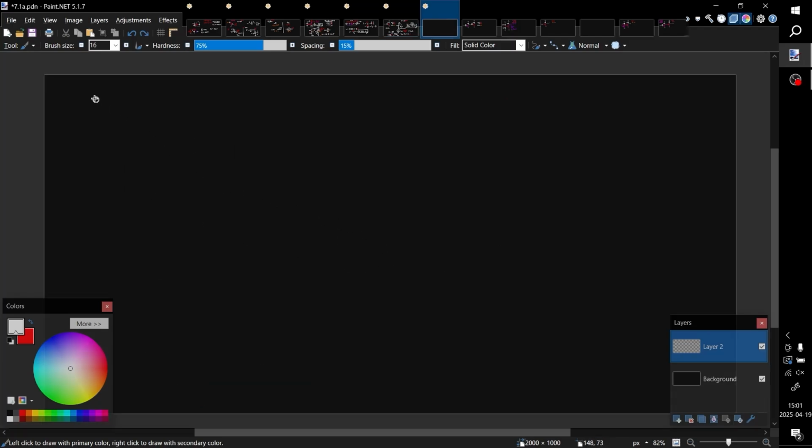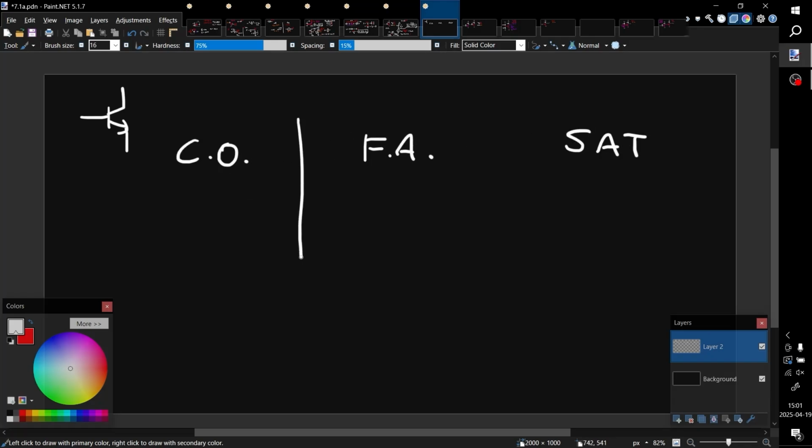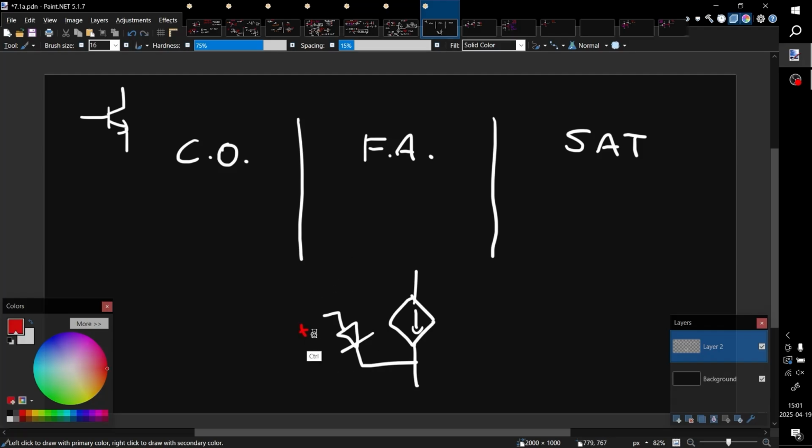To do BJT analysis, this is what a BJT looks like, by the way. It has 3 states. We have cutoff, forward active, and saturation. I'm gonna draw the forward active model here. It has a diode and then a dependent current source, which depends on this diode. Wait, before I do the checks, do you know what these terminals are called? My mnemonic here is comeback era. CBE. Collector base emitter is comeback era.